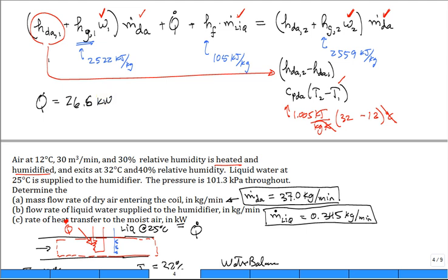It's shown into the system, and so it's positive. If I look at how much heat was required to heat the dry air, the equation for that is the C sub P of the dry air, delta T of the dry air, times the mass flow rate of the dry air. I calculate that energy, just to heat up the dry air, about 12.4 kilowatts.